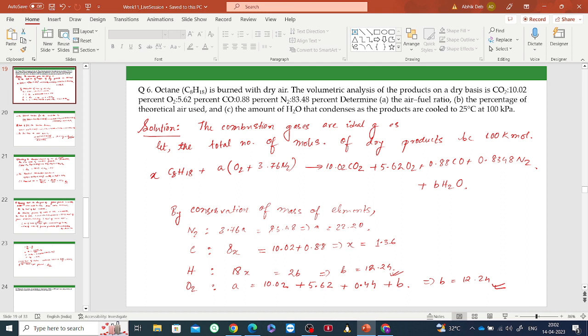Okay, so like the enthalpy of this carbon dioxide at the specified state, let it be like 100 kPa and 25 degrees Celsius, that at 100 kPa and 25 degrees Celsius the enthalpy of formation of carbon dioxide will be the enthalpy of this carbon dioxide at this specified state due to this chemical composition, that the carbon and oxygen are linked together in this manner. That is why what will be the enthalpy with respect to some standard state. So what is the standard state?